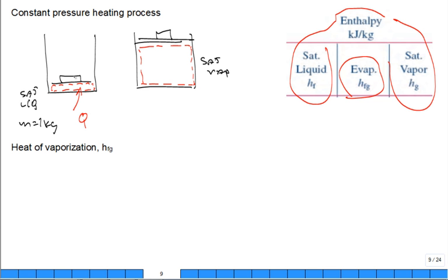Frictionless piston, the elevation of the piston went up, but the weight didn't change. Does the weight depend on elevation? You know, I'm standing on the floor, I weigh so much. If I stand on the table, does my weight change? Is my weight different? Weight's independent of the elevation. The weight of the piston is independent of the elevation, hence the pressure of the gas under that piston is independent of the elevation of the piston. So it could expand at constant pressure, true? It expanded at constant pressure. So what you do is you write a first law for the process.